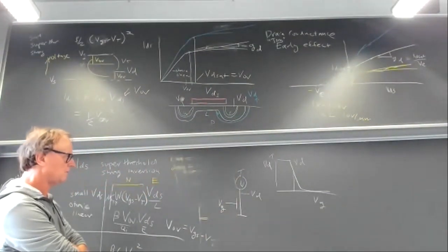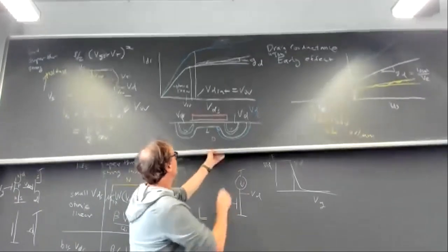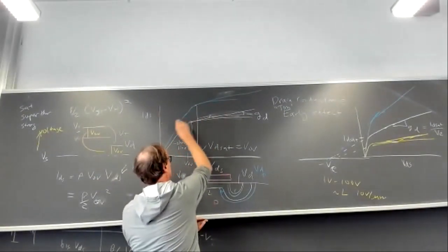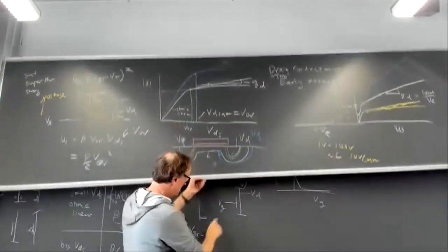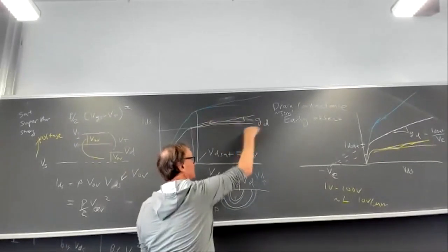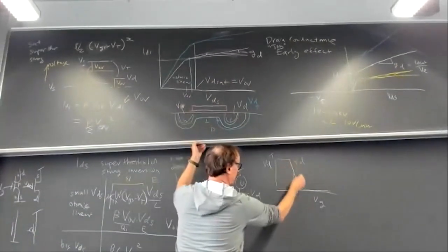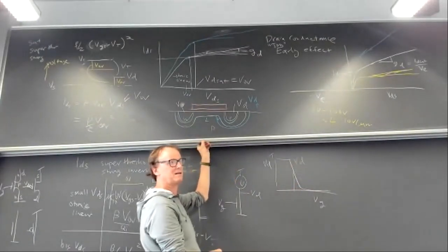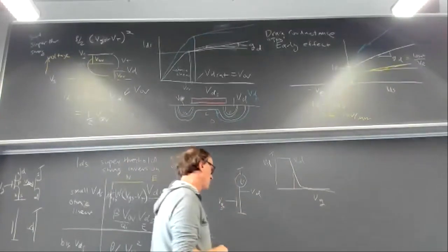Yeah, but there'll be a critical region in here, exactly this region, where the saturation current through the transistor is approximately equal to the source current, where you'll be sweeping along this drain curve. And then the slope here will be determined by the drain conductance and the gate transconductance. Let me draw the equivalent circuit, and then perhaps that'll make it more clear.